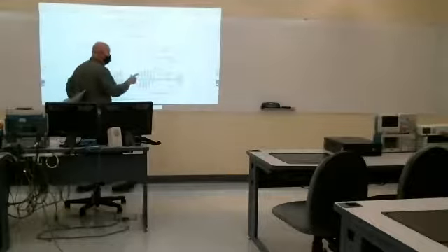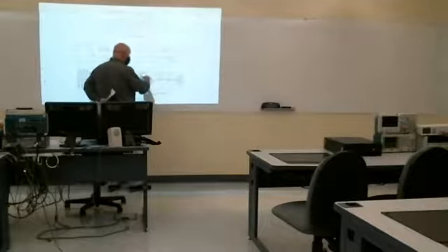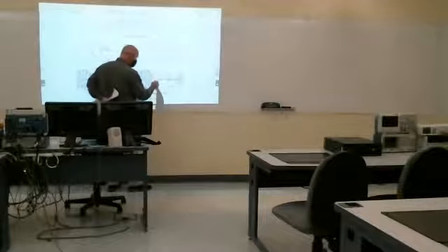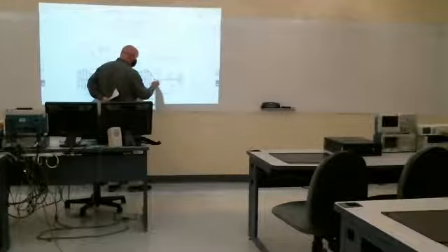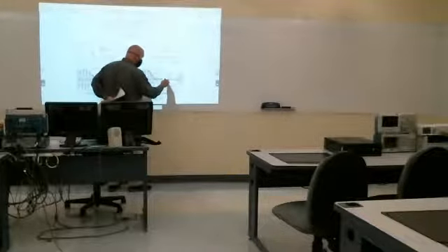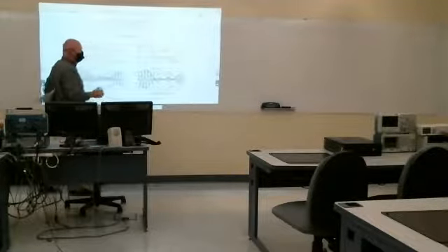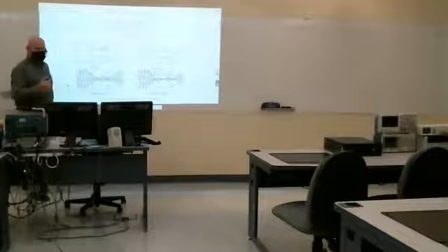But if A plus x(t) is not always positive, our envelope, our A plus x(t) signal would actually continue on here, but the envelope, which is following the positive peaks, would look like this. Okay. It would be a distorted version of our waveform.